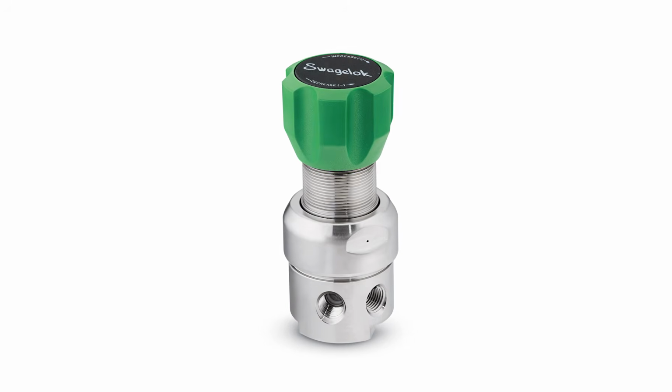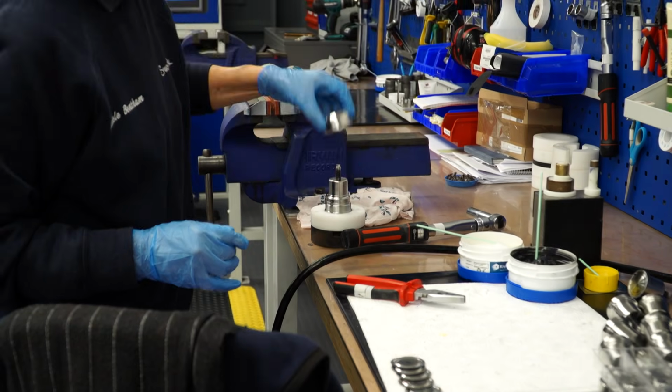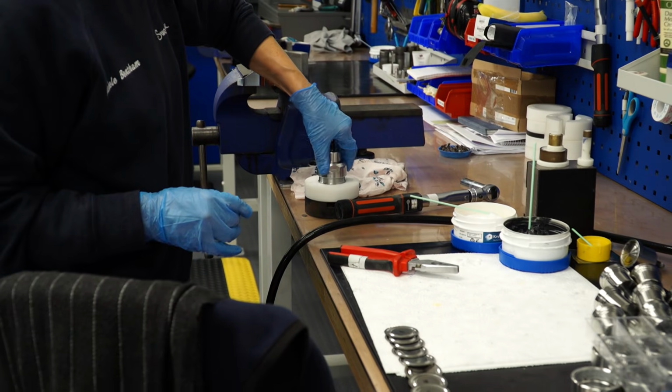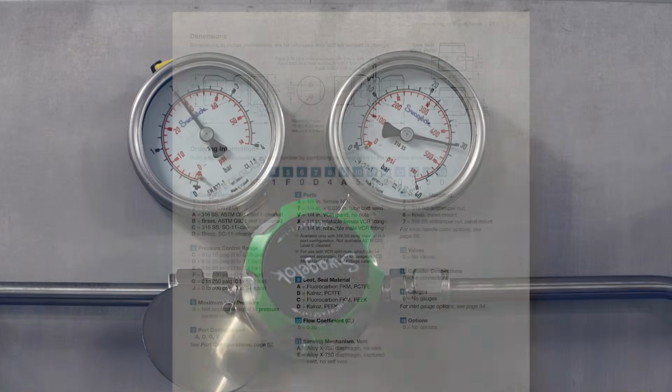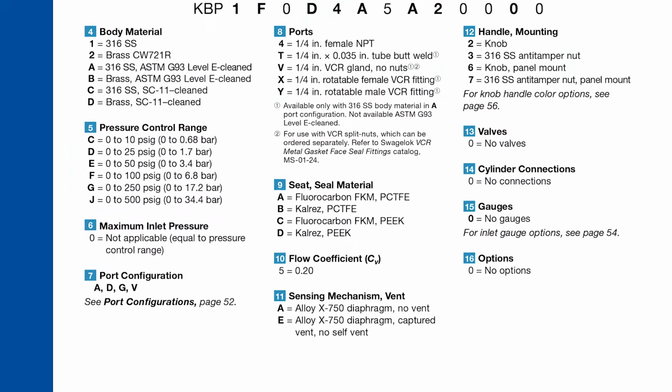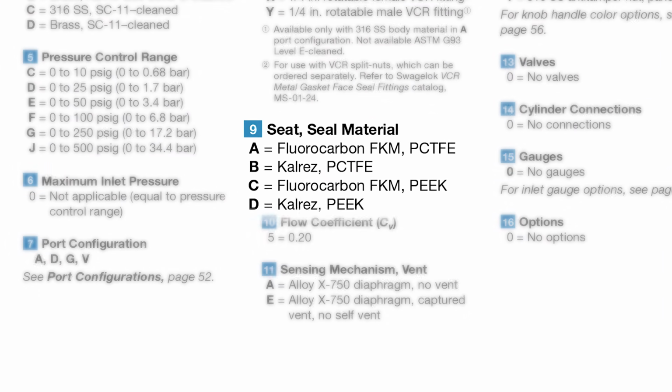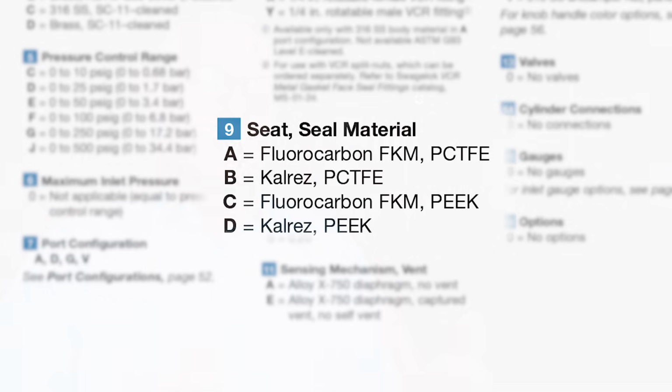The material compatibility is important. So inside regulators are elastomers and polymers. Elastomers are O-rings. If these materials can't handle the fluid which goes through the regulator, we have to select a material which can handle the fluid. So material compatibility is also important to know what is your highest temperature. If the customer is using a regulator at a very high temperature and our O-rings can't handle that high temperature, we have to advise him to select the correct materials in the O-rings.